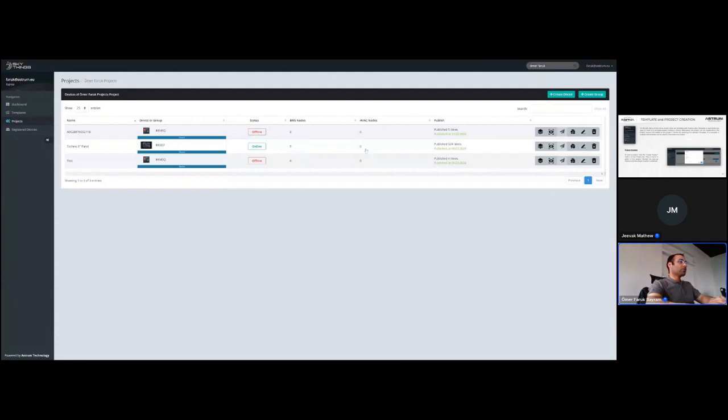And for HVAC nodes with VRF controls, every indoor unit is one HVAC node. For example, if we use an add-on VRF solution and control our system through an outdoor unit, and one outdoor unit has 8 indoor units, that means we have 8 HVAC nodes. So we need to use an HVAC node license on this device as well.